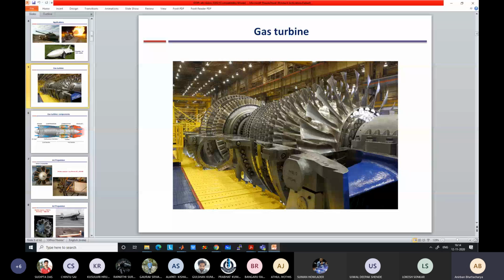So what happens to the stresses that are generated? They are high for those long blades. They will be much higher because the rotational speed is the same. If the rotational speed is the same but the tip velocity keeps on increasing, meaning the diameter keeps on increasing, you will get higher centrifugal stresses. Then you need better and more costly materials, or thicker blades. Somewhere the cost is going to increase.